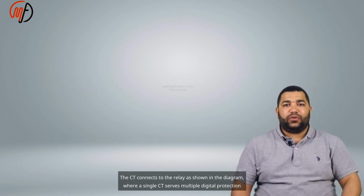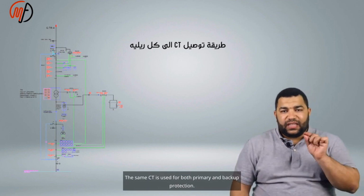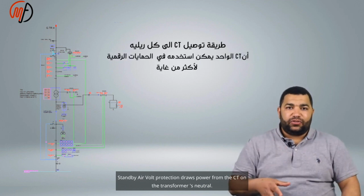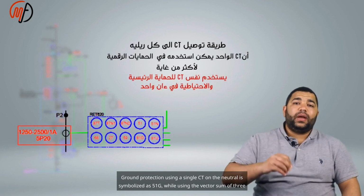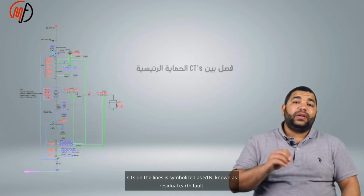The CT connects to the relay as shown in the diagram, where a single CT serves multiple digital protection purposes. The same CT is used for both primary and backup protection. Ideally, CTs for primary and backup protection should be separate. Standby earth fault protection draws power from the CT on the transformer's neutral. Ground protection using a single CT on the neutral is symbolized as 51G, while using the vector sum of 3 CTs on the lines is symbolized as 51N, known as residual earth fault.